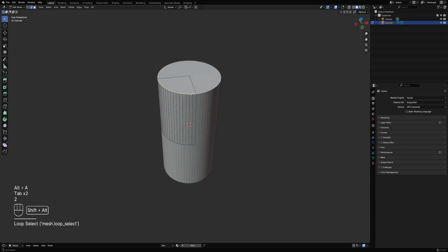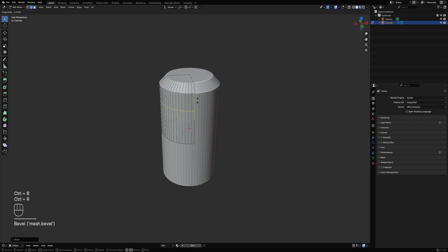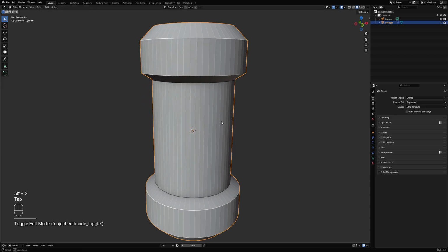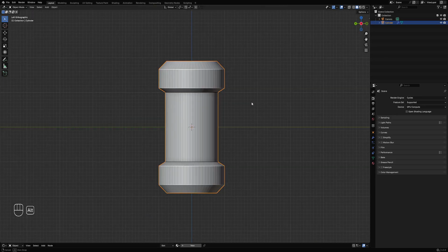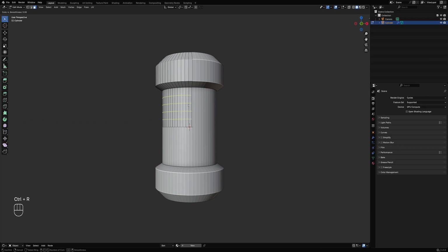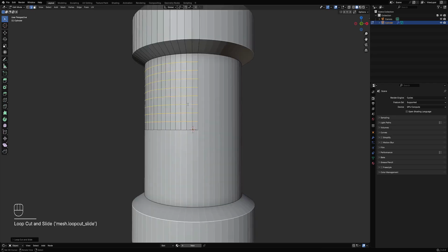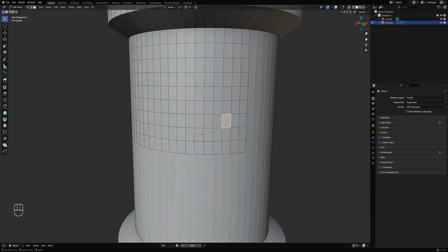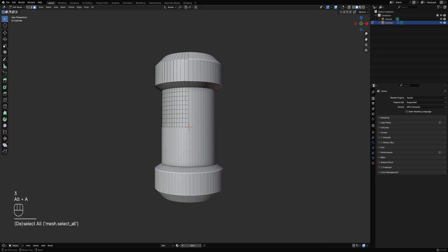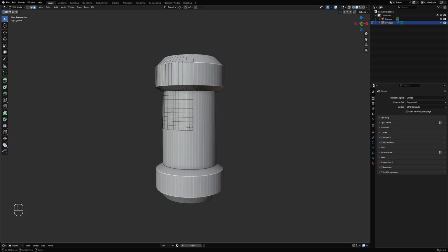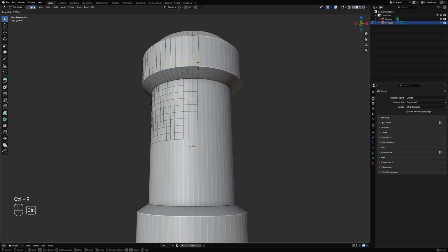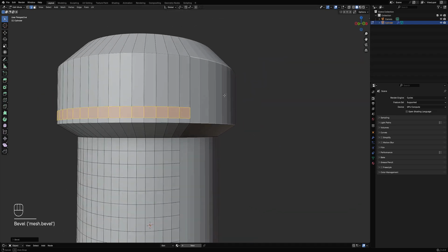Okay, and let's just design the base. So mostly quads because the randomization only works with quad faces. It can also work with tris, but the randomization pattern, of course, is affected by topology. So being quads and being mostly evenly sized quads is really great. So in this area, I'm going to create a cloth. I use the panel cloth operator to create a cloth detail, while the rest will be using just the random mesh or randomized mesh.